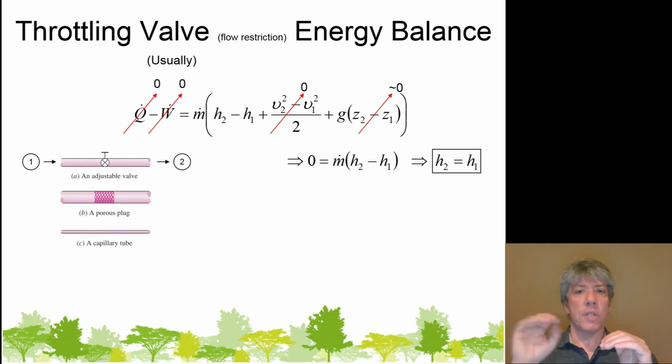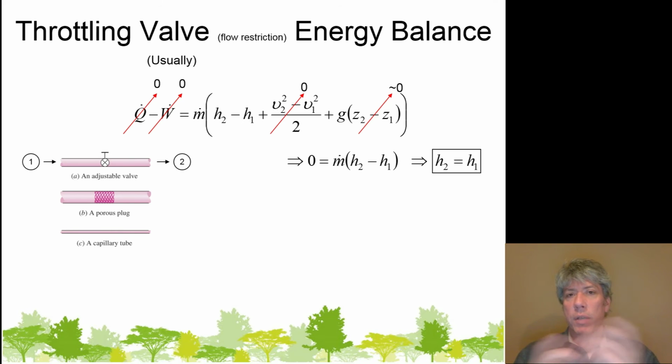When that happens, the temperature of both the liquid and the vapor that's leaving in state 2 will be at a relatively low temperature. And so if you think about what's happened from inlet to exit, forget the phase change for just a minute. Because the temperature has gone down, there has certainly been a change in internal energy, right? Not to mention the phase change itself, which represents a change in internal energy, even though it's not a sensible change, it's a latent change, right? So certainly there's been a change in internal energy, but what happened?